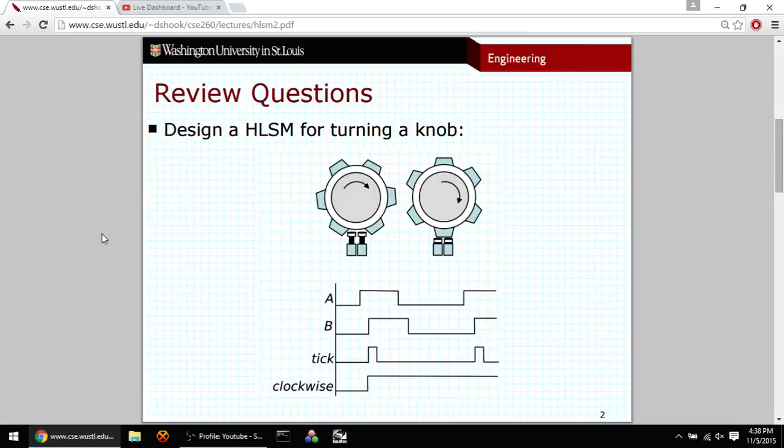Maybe if they're the same. If they're the same as they were previously, then we'll just hang out here. So AB is equal to previous button press. And there's probably a self loop here, I imagine, with the same, right? As long as they're not changing, then we're just going to hang out. We haven't set any outputs yet, though, right? That's a pretty glaring omission.